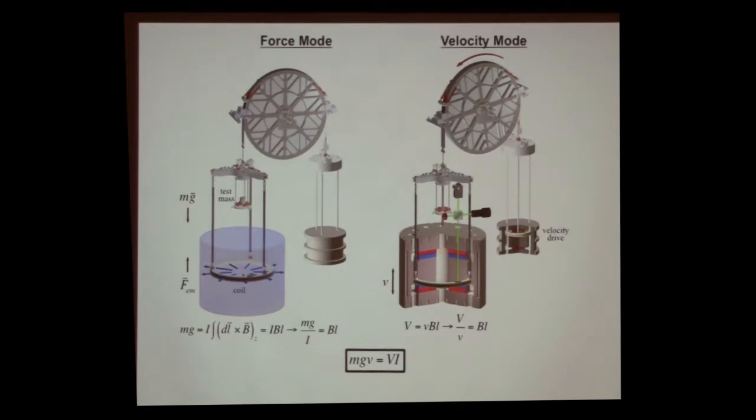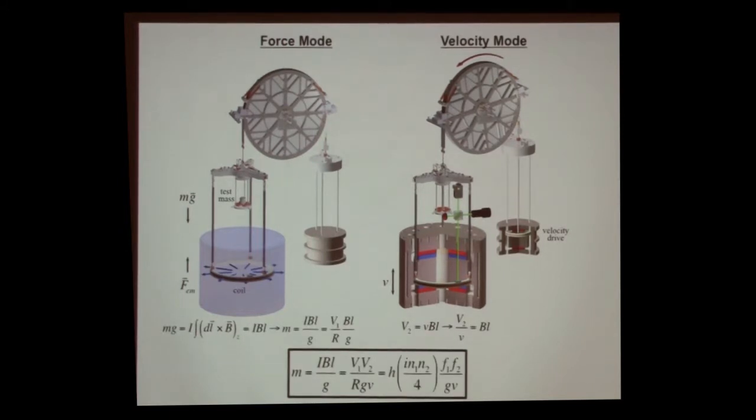Now what's somewhat important, and one of the tricks of the watt balance, is that this force mode is done when there's no mechanical motion. You cannot have frictional forces or dissipative forces in your balance, otherwise it would kill you. And in the velocity mode, likewise, your meter reading the voltage has an incredibly high input impedance, so there's no electrical dissipation of energy. So this is really a virtual watt equation, but this is why it's called a watt balance.